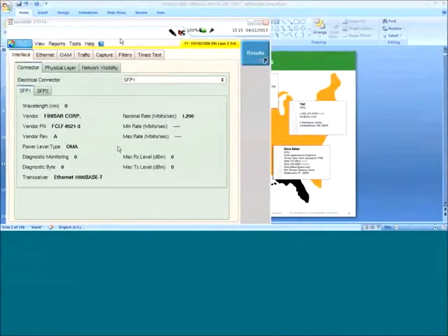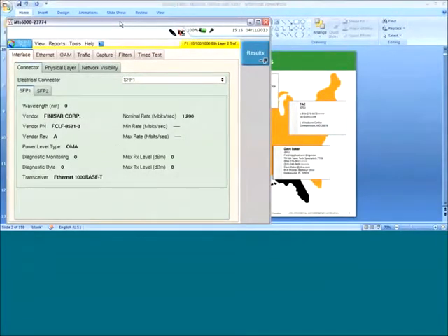Okay? Yeah, so there you go. Somebody offered the proper answer. So you don't want to damage your vision. I like that. So there you go, fiber, unless it's heavily padded. So it's better to have it not lit when you're doing a scope test, okay? But yeah, essentially, if you want to see the right proper dB level, all you do is insert the optics into the test equipment, and then it will tell you the max values.